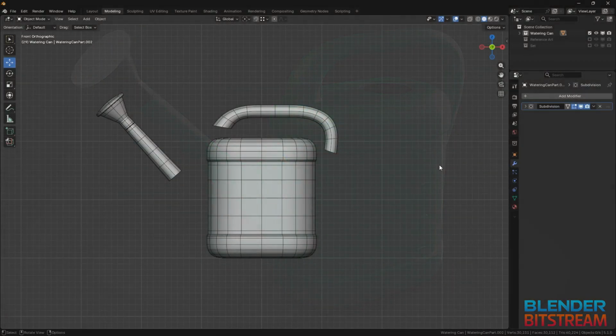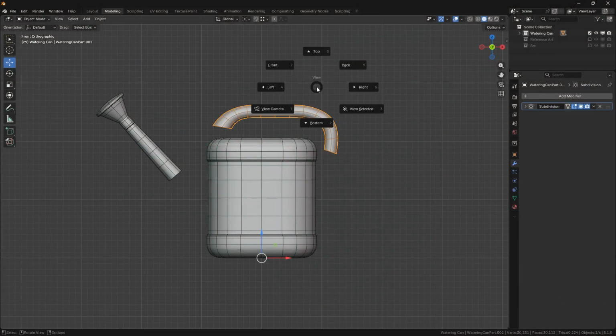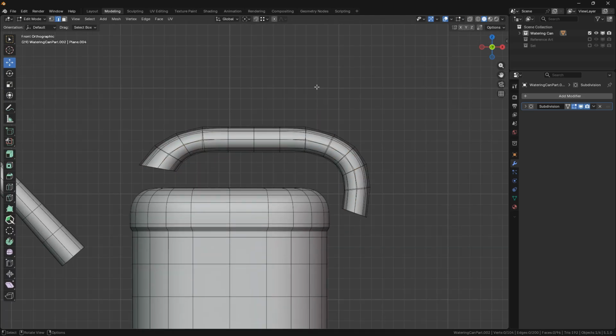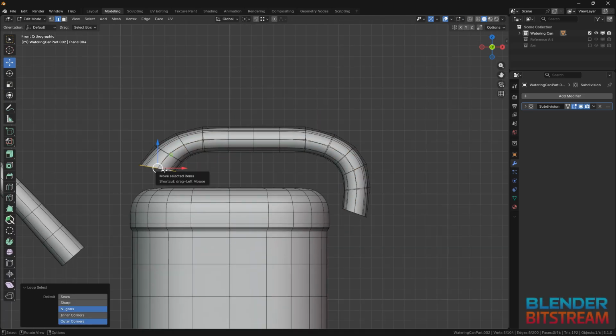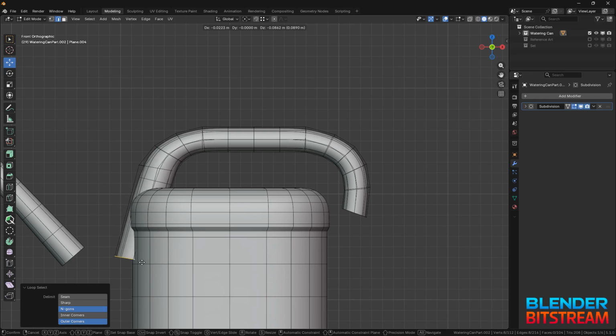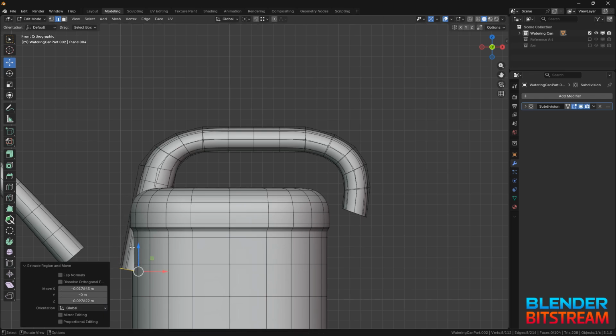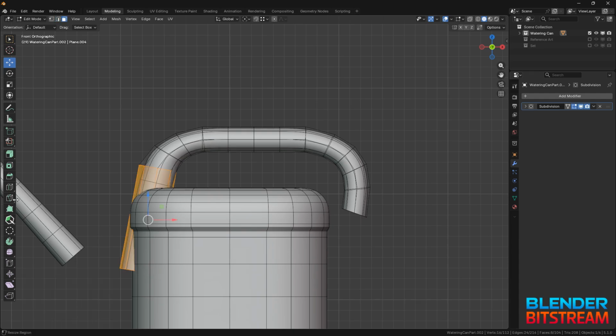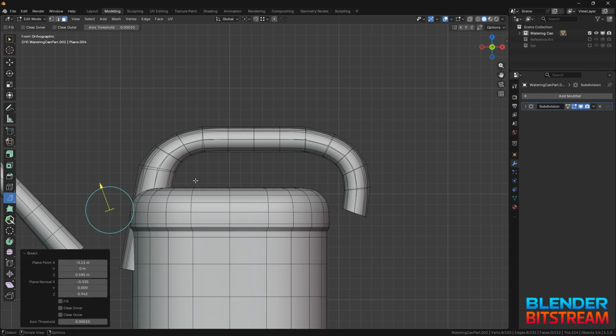is incredibly useful. I'm starting with a plastic watering can that has a few mesh areas that need to be joined. So I'll begin by selecting the handle mesh and switching to edit edge mode. With the end loop selected, I press E and pull the extrusion straight through the main body so it passes through the mesh. Now if I press Ctrl 3, Blender converts the selected edges into faces, and I can use the bisect tool to cut a line that runs roughly parallel to the surface.